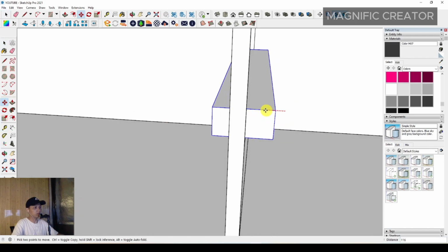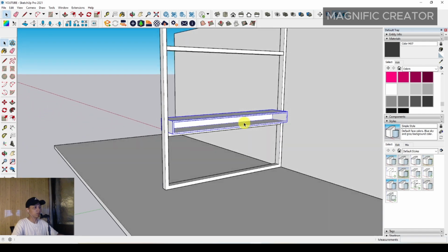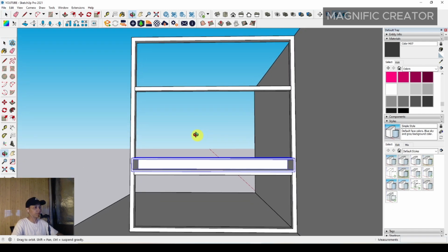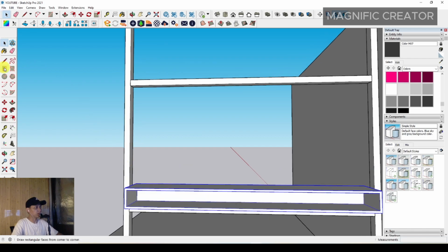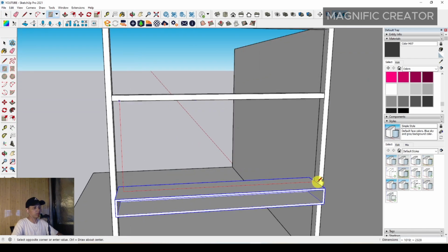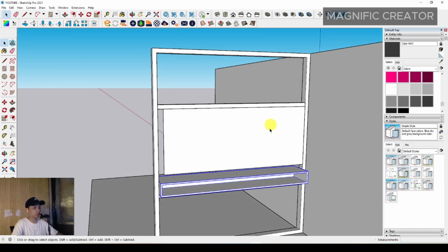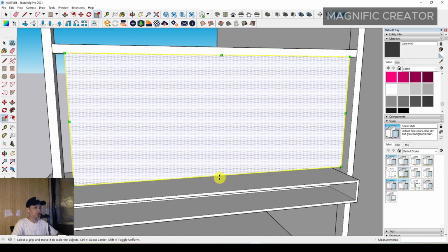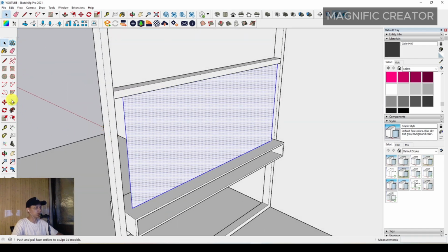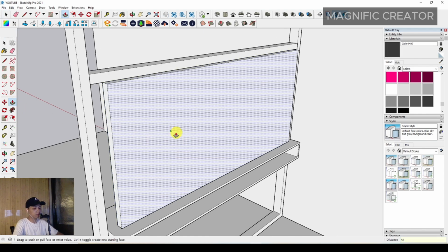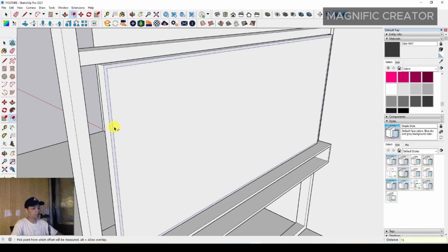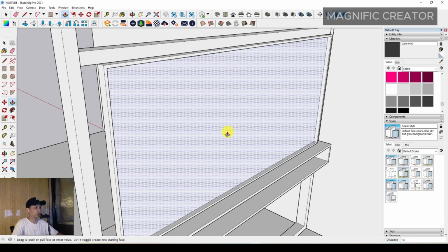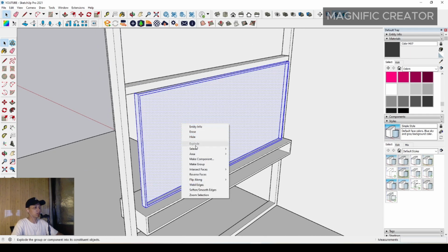and then we can move it to the back to make a balance, and then we can make the pivot. We can make the pivot TV cabinet itself anyway. Okay, we can set it with any size of rectangle, then we can adjust it. We can position it, and then we can push it front around 50 millimeter. Then we can offset it around 15 millimeter only, and then we can push it back around 40 millimeter. Then we can make a group.